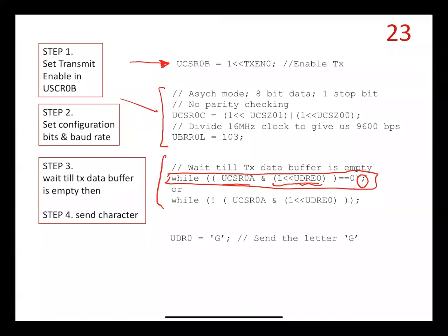Let me show you a different example altogether. Suppose I wrote this. We know that we've been working with this super loop for a few weeks. Let's say PORTB XOR equal 1 shift left. We've used a command like this for a while. This will toggle the internal LED. This construct, a while(1) is always true, toggles that LED.